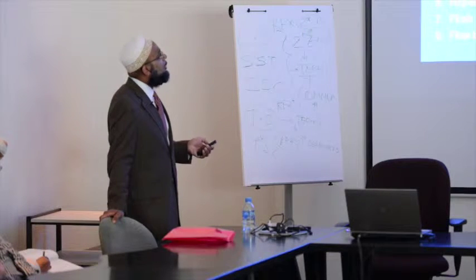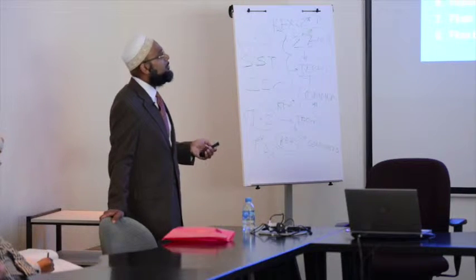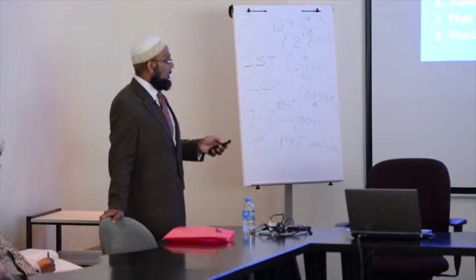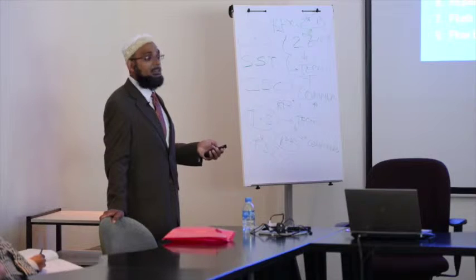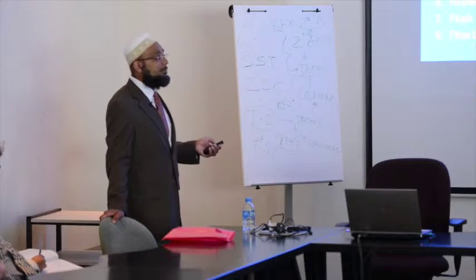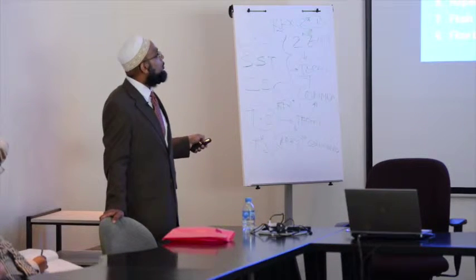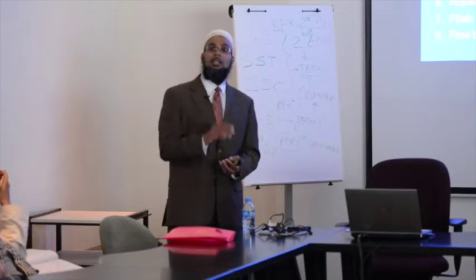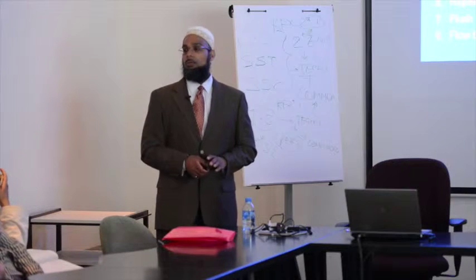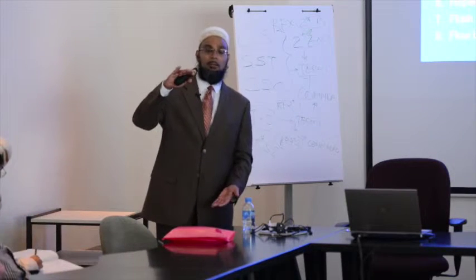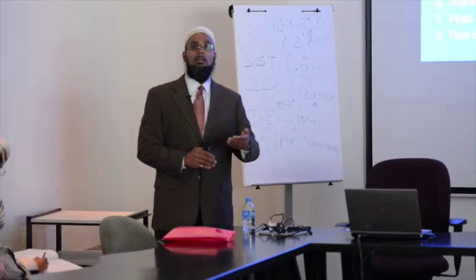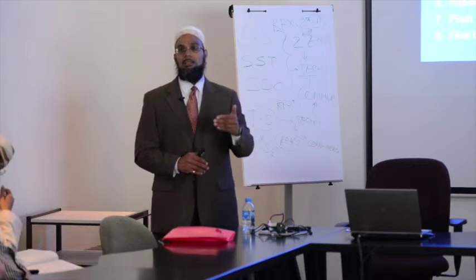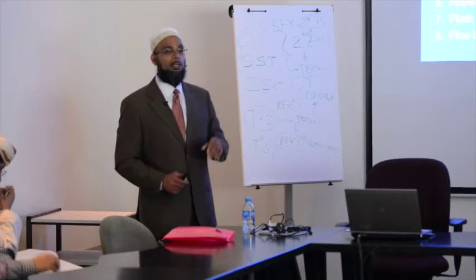After this, we go with acid injection. Acid injection is maybe 10 to 28% hydrochloric acid, which is very common. For high temperature, we use organic acid and chelants also. Then there's a diverter stage. And what we do is we repeat steps 4 and 5 for every 20 to 30 feet of formation. So if you have a 100-foot thick interval, you will have 5 stages: acid, diverter, acid, diverter, acid, diverter, like that, right? For every 20 feet.